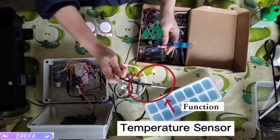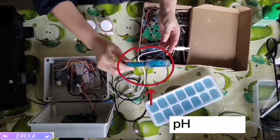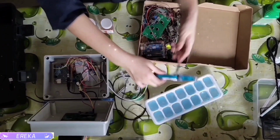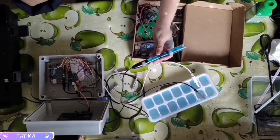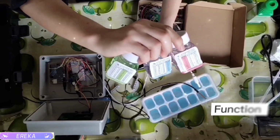The water temperature sensor is used to measure the water temperature inside the fish tank. The pH sensor helps to measure the acidity or alkalinity of the water with a value between 0 to 14. The pH sensor calibration solution is used to calibrate the pH sensor.